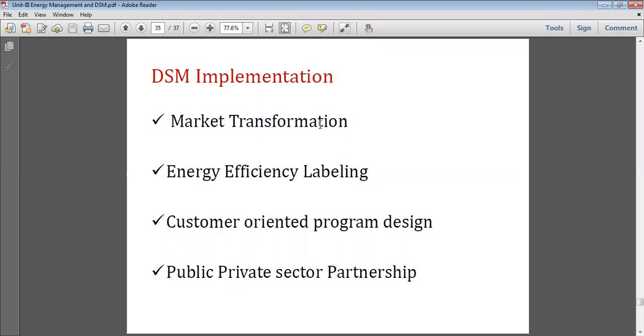If you are going to use a fluorescent lamp in your home or office or somewhere, you find that the cost of the fluorescent lamp is hardly 45 to 50 rupees. That is the fluorescent tube. Now see what the output lumens from that particular tube fitting are. You will find that it consumes 40 watt or 36 watt, and the lumen output is 1800 lumens, the gross lumen output by the light source.